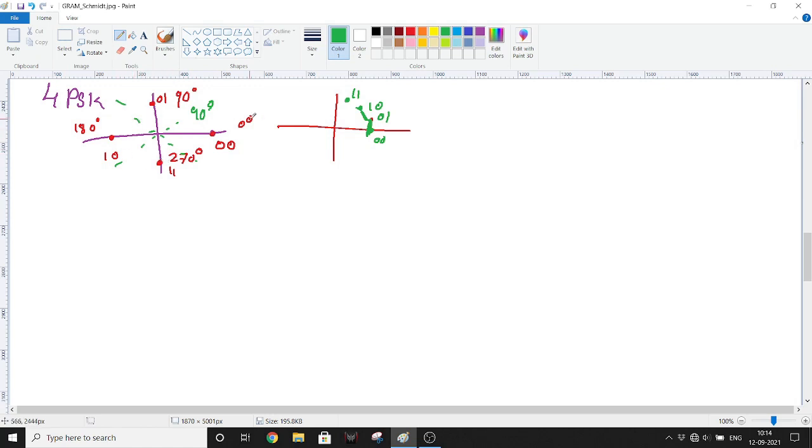The same thing goes with higher M PSKs. So whatever the M I have, it is 360 degrees divided by M. So whatever the angle I receive, that is the spatial difference between the PSK symbols for achieving the best modulation, that is, to get the least amount of error for that given modulation scheme.